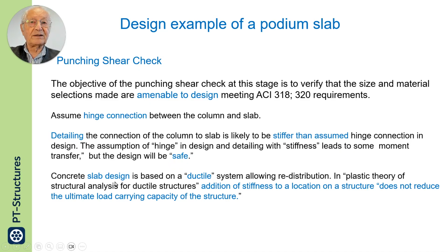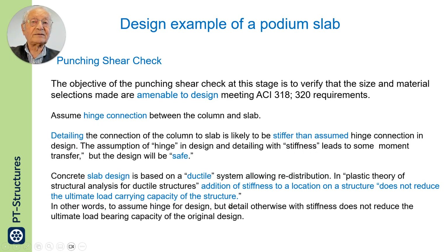Concrete slab design, that is the argument for it, is based on a ductile system allowing redistribution. In plastic theory of structural analysis for ductile structures, addition of stiffness to a location on a structure does not reduce the ultimate load carrying capacity of the structure.